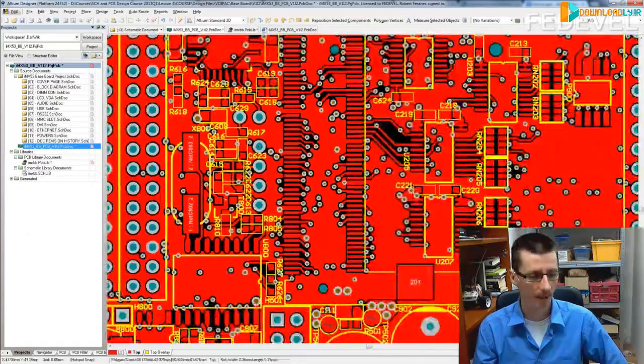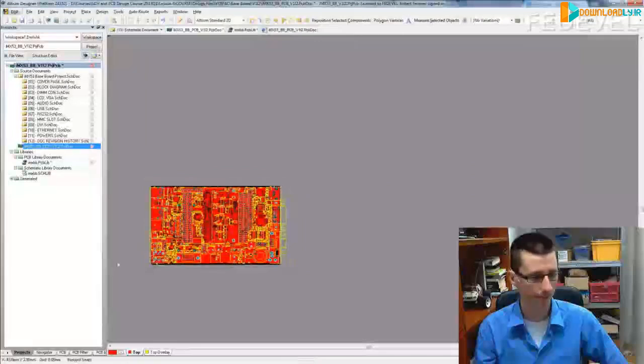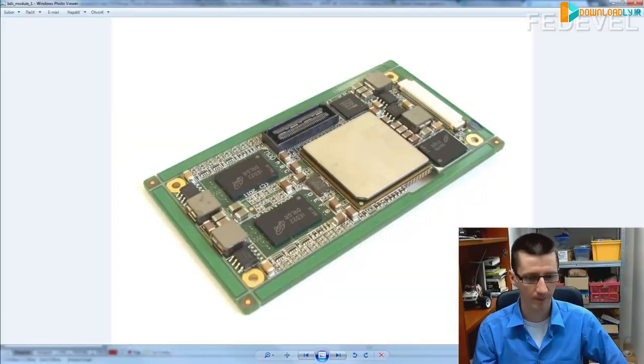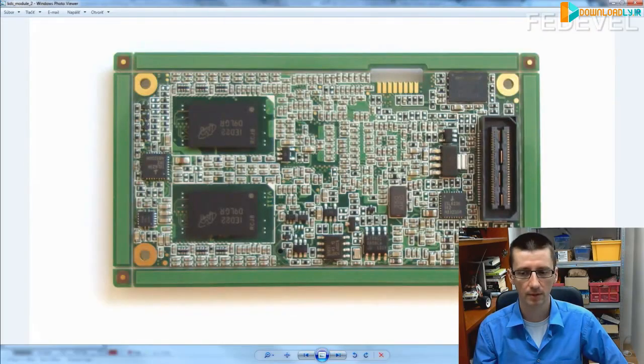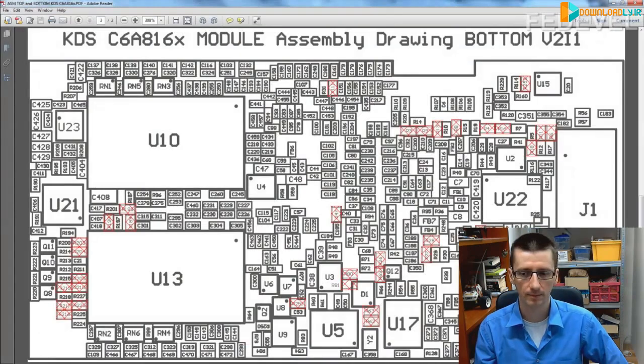But for things like this, one of the boards I designed, have a look at the bottom side. Yeah, there is no space. How do you identify the component? When you send this kind of board into production, how can they check the position of the components? They need something to tell them where each component is located. That's the assembly drawing. It looks like this.